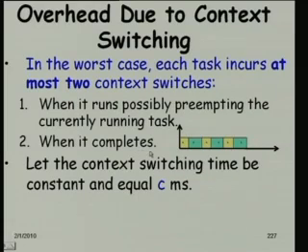Let us look at the diagram here. A higher priority task has come in here, and this has 2 context switches taken care of. One is, this task started coming in here at this point, there was 1 context switch. Next time this task has preempted it, and this context switch will be counted towards it, which will be taken care of in our expression, because it is a higher priority task, and then it started running again.